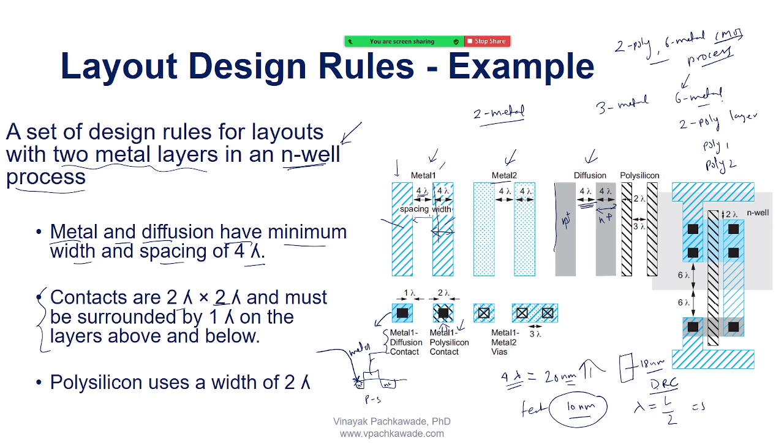These contacts are showing the metal 1 and metal 2, that is called vias. Okay, what is metal 1 and metal 2? How do they connect together? Let's say I have this metal 1 here, this is cross section, metal 1, and this is metal 2, let's say M2, and this is M1. So these two metals will be connected through a special contact, they are called a via. So that's again the electrical connection. We'll see what via is when we move forward.